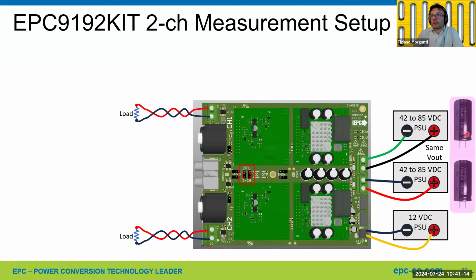It is often recommended to add a couple of big capacitors in parallel to the power supplies. We have seen during our measurements regulated power supplies going crazy because of the current ripple flowing when you run the amplifier at low frequencies, like 100 Hertz and below. So it's recommended to place a couple of 2,200 or 3,300 electrolytic capacitors on the power supply connectors.